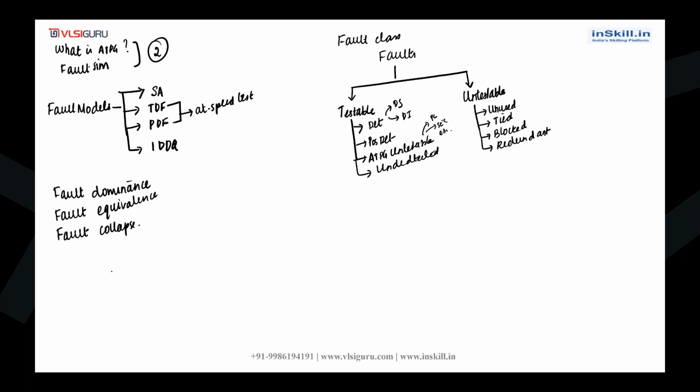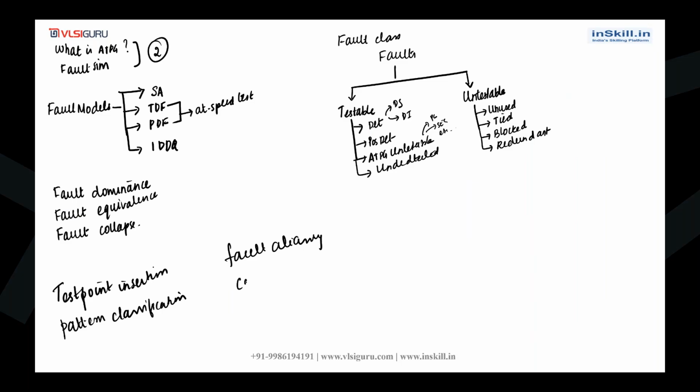Then we will try to understand test point insertion. What is test point insertion? We will try to understand pattern classification, and then fault aliasing, and then what is called coverage, what is test coverage, what is fault coverage. All those things we'll try to understand.